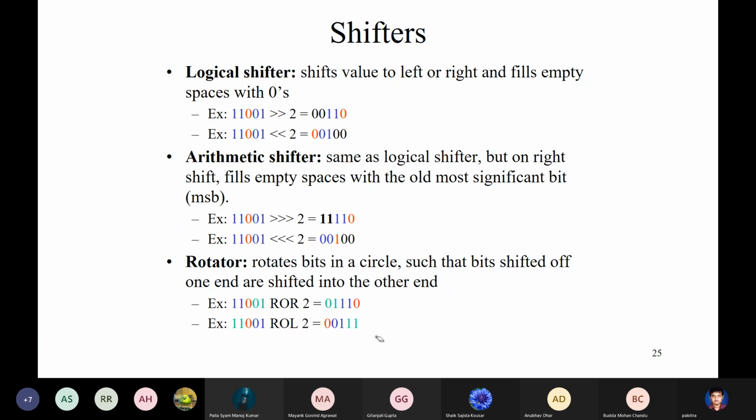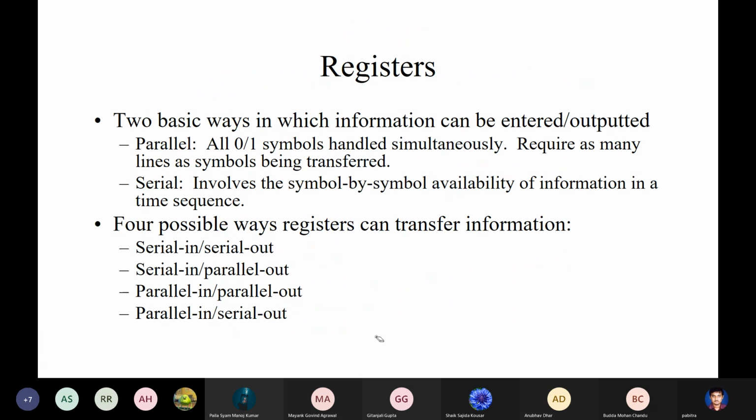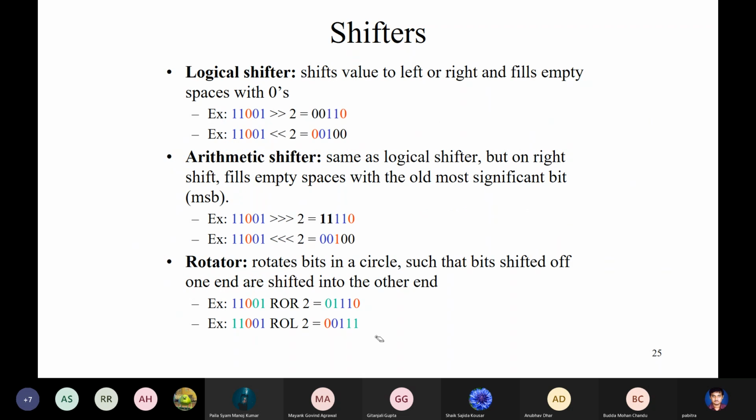Okay. One more thing, if we're looking at serial in or serial out, then this shifting from serial can happen in different ways. You can imagine in serial in, the values will come in, and one by one this will propagate to the flip-flops. So this propagation can happen in the following three different ways. Each has its own application.